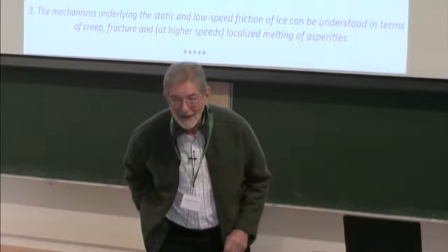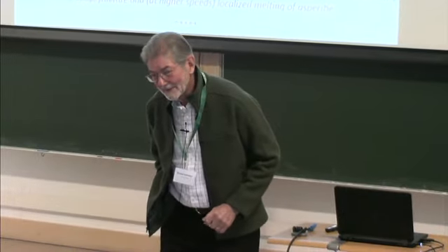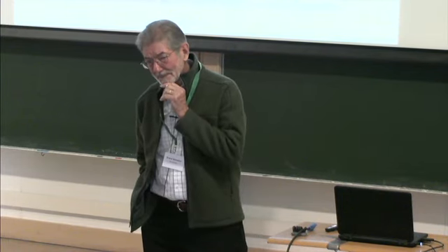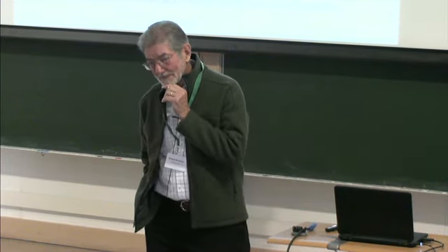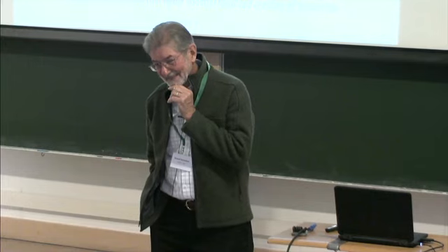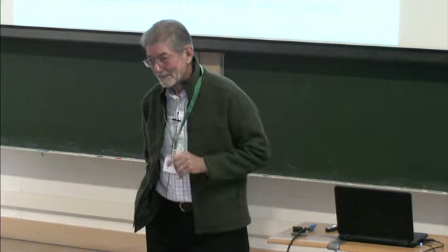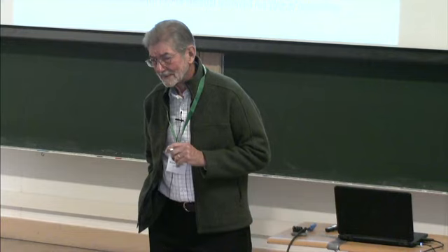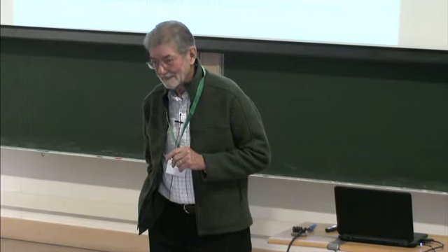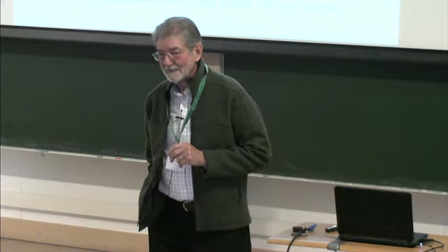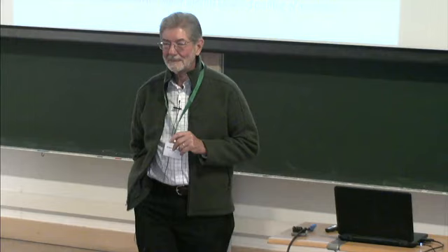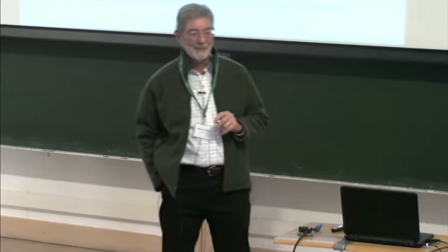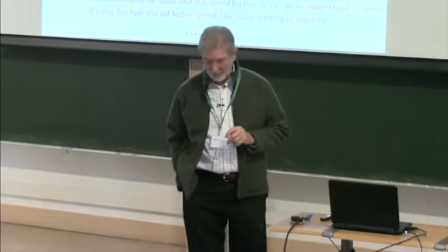Very nice talk. Thank you very much. I was just wondering about the local strain rate for these asperities, because they're so small, it actually is quite, I'm not sure what it would be, but I imagine it would be quite high. Just wondering if you've looked at whether there are potentially fracture processes and breakup at the interface when you get into higher regimes? Because as the speed increases, I wonder if there is some relationship there with the transition from more ductile or creep-dominated behavior to perhaps some localized breakdown as well, which you would see in the field.